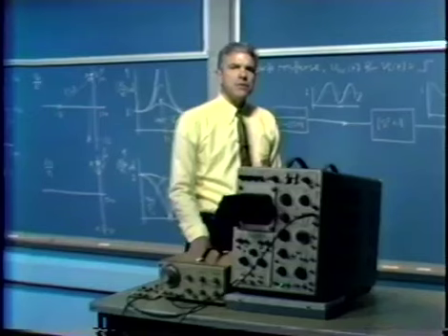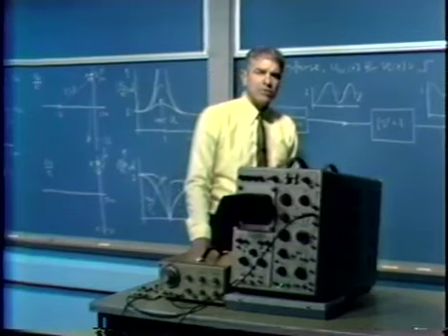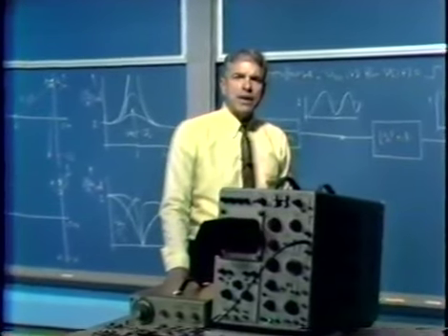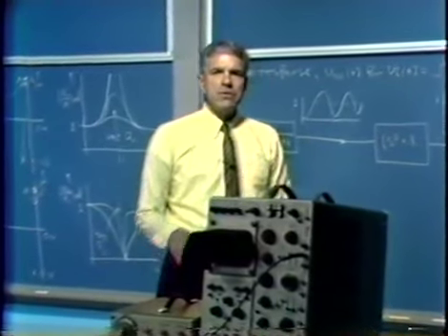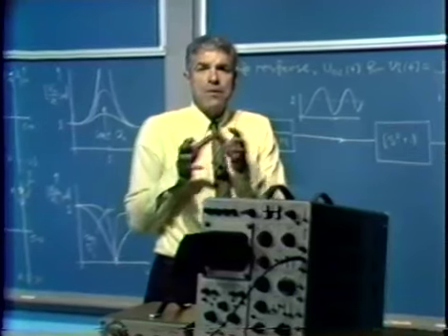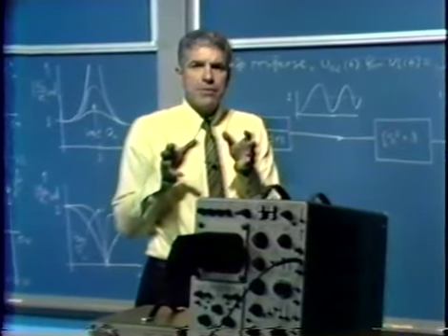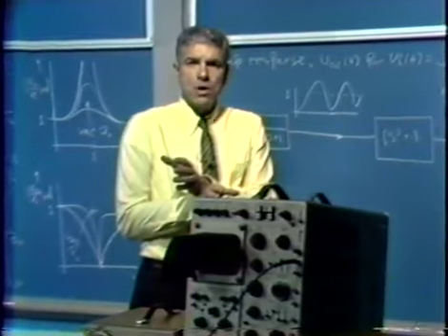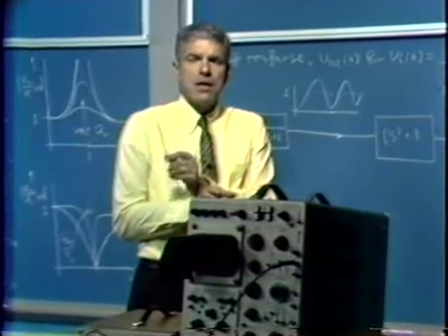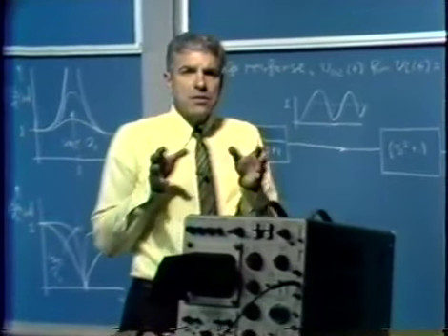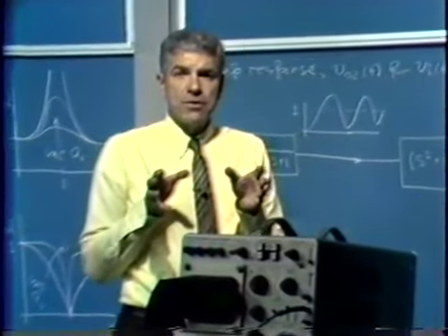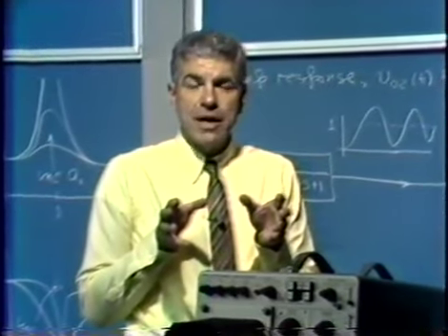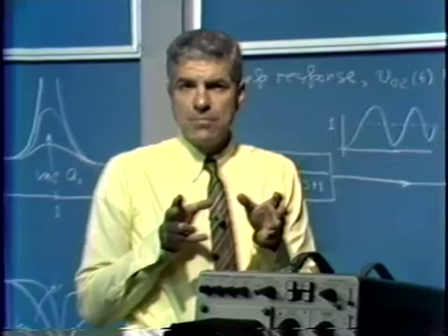It turns out what we can do to estimate the response of the rejection amplifier is exploit a property of linear systems. If we have a linear system, we're able to, conceptually at least, shuffle the blocks in a block diagram in any order that's particularly convenient for us. And what I hope to do is choose one that's fairly easy for analysis. And so what I'd like to do is consider the overall system transfer function for the rejection amplifier, which includes a pair of zeros on the imaginary axis and a complex conjugate pole pair.